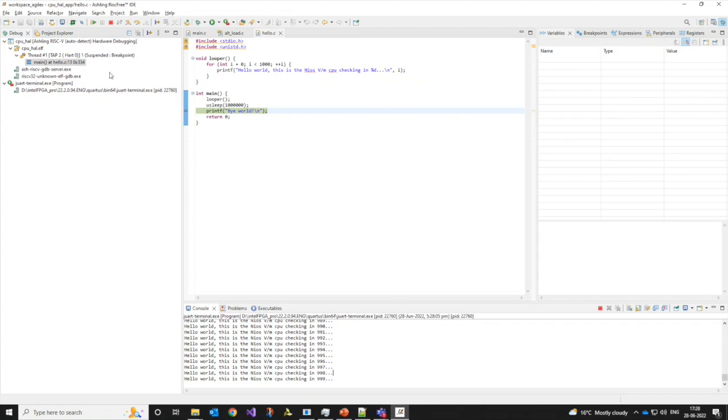So I'm not going to other debugging because all the debugging features still remain the same. I just want to show this capability of building the HAL application from within RiscFree. And the difference, the first one was make based and this is CMake based. So covering those two as well. And so this was the second phase I was discussing that we would cover in the live demo. And the third phase is the heterogeneous debugging, which means I'll be simultaneously debugging RISC-V and ARM.